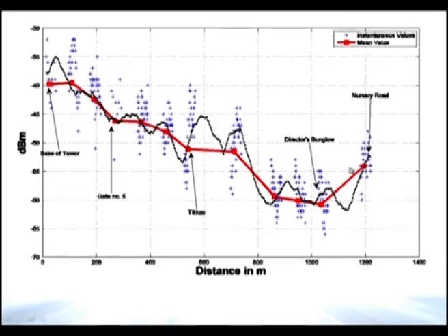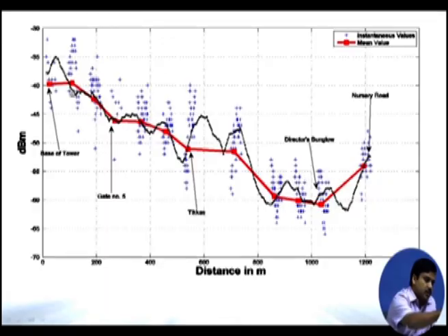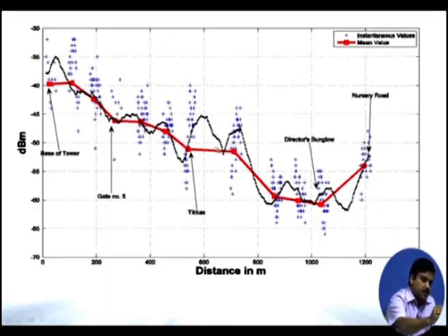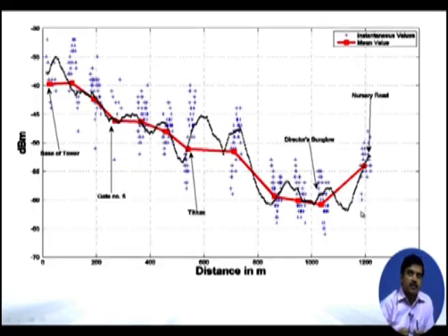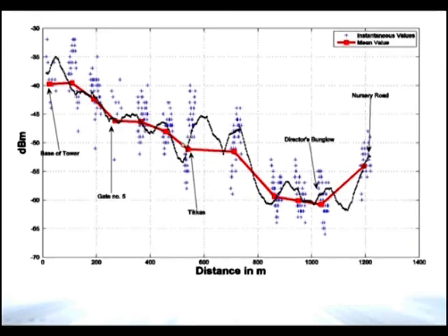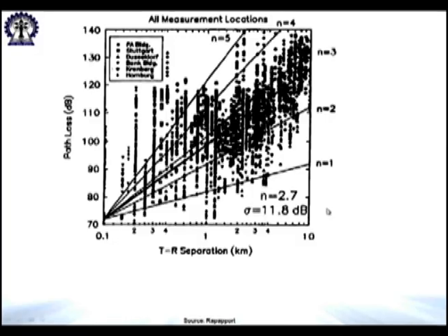If it was only path loss in nature, we would have expected a straight line in this direction with a particular slope. However, what we have received is fluctuations, where signal strength goes down and then again goes up, and could again go down, but on average there is a decrease across distance. To cater to these local fluctuations, as we are seeing, we need to improve upon the model which we have discussed until now. Now, this result is again from Rappaport.